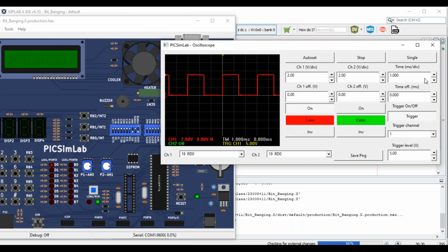Okay, so can you observe here? The time I have taken is one division of 1 millisecond. If you properly observe, let me highlight this much. It's occupying 3 divisions for 1 pulse. Can you see that?